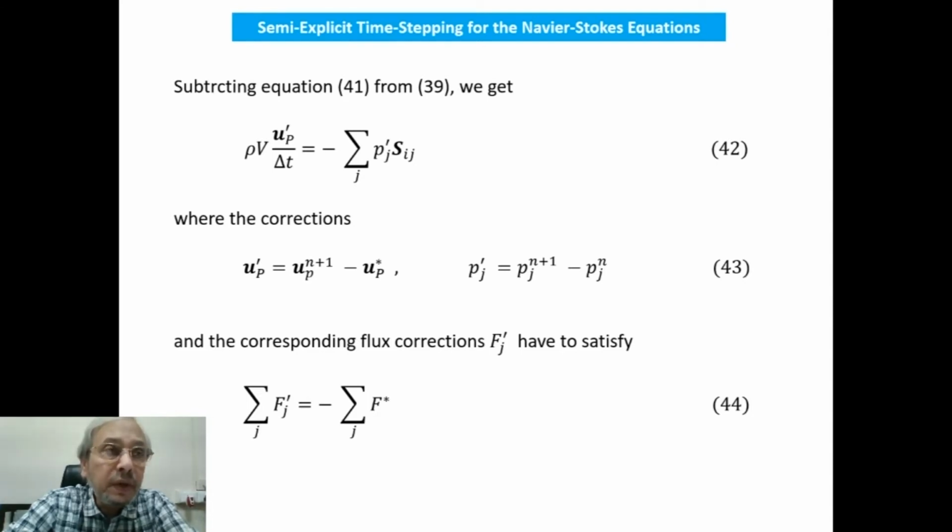So these velocity quantities in each cell, u, v and w, are provisional velocities, and there is a difference between this provisional velocity and the final velocity u, v, w at n plus 1. This difference we can call the velocity correction.